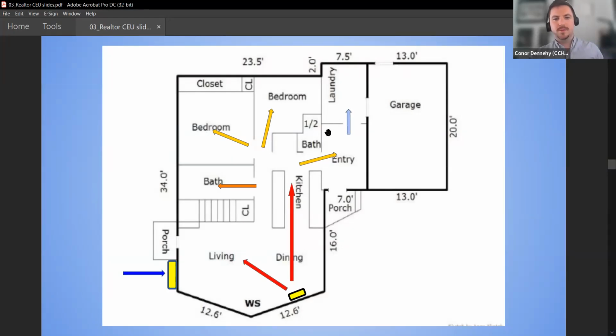This can be solved a couple different ways. You can actually get a configuration that has multiple indoor heads attached to the outdoor unit. And that's great, you'll be able to serve more places. The caveat to that is the more heads you add to a single outdoor unit, the less efficient it will become. So you can tackle this a second way and say, I'll just get 2 single head systems. And that's great.